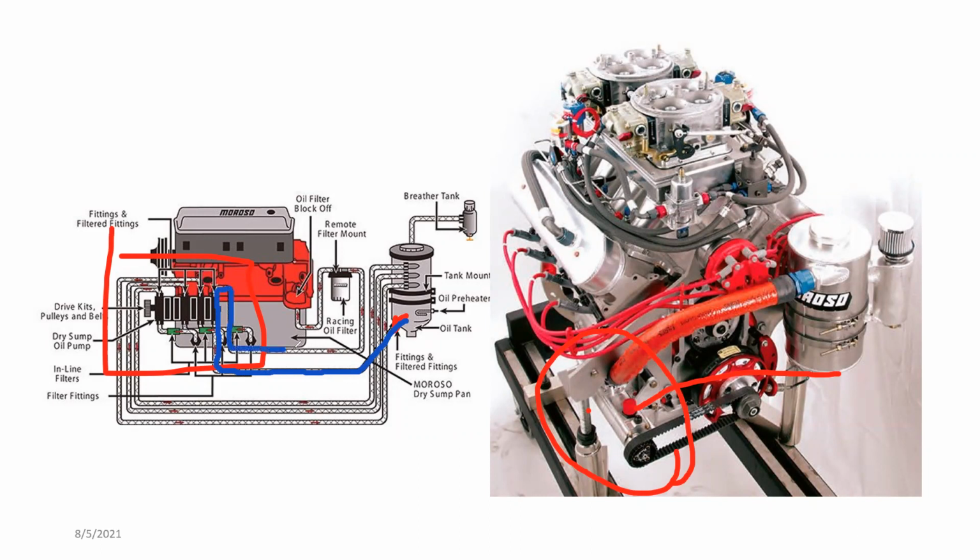That pressurized oil is next sent through another filter, then it goes to the engine oil gallery. So this is how a normal dry sump lubrication system works.